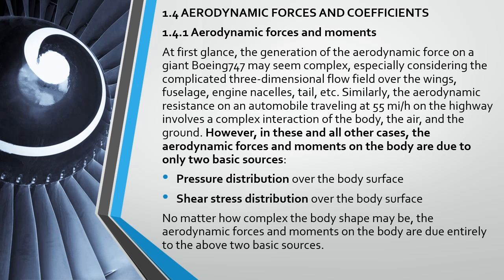However, in these and all other cases, the aerodynamic forces and moments on the body are due to only two basic sources: the pressure distribution and shear stress distribution over the body surface. So no matter how complex the body shape may be, the aerodynamic forces and moments on the body are due entirely to the above two basic sources.